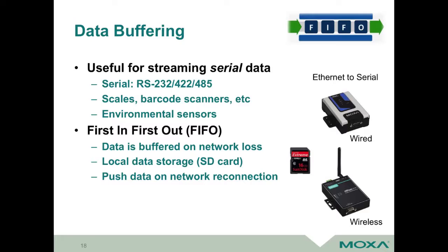In some of these, when you've got the real simple protocols, one of the applications I've seen this used a lot is in oil and gas, where they've got telemetry streaming off of a wellhead or a drilling site, and they have a problem where they lose their satellite link when a big thunder shower comes through. That happens. It's not perfect technology. Data buffering can be useful in those applications. If you've got the right hardware to support this, and you've lost your communications path, your connectivity device is able to keep grabbing that data and store it and hold it, and when the network comes back up, unspool and push that data back up to your server to capture it.